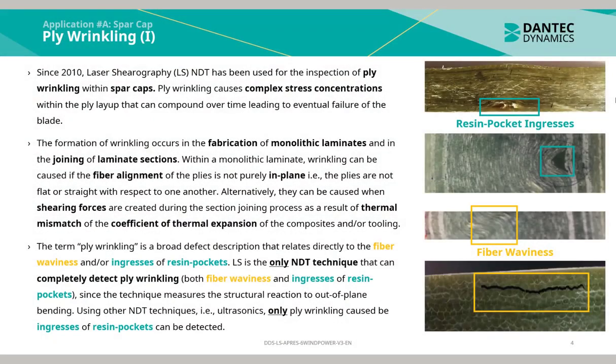Ply wrinkling. Since 2010, laser shearography NDT has been used for the inspection of ply wrinkling within spar caps. Ply wrinkling causes complex stress concentrations within the ply layer that can compound over time, leading to eventual failure of the blade.